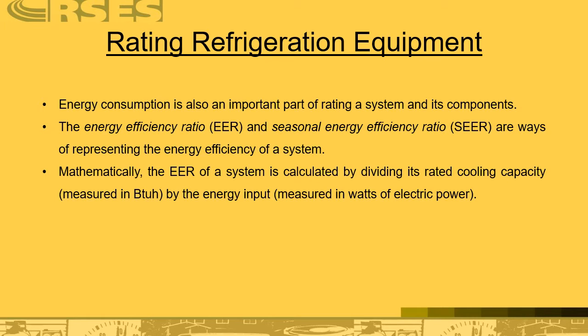I will tell you this, in California, if you're going to put in a new split system or a package unit air conditioning system, 14 is going to be the magic number as far as the seasonal energy efficiency ratio. So the higher that number is on that yellow sticker, which is required by federal law to be attached to all cooling equipment, basically that means the less amount of power that is needed to make that process happen.